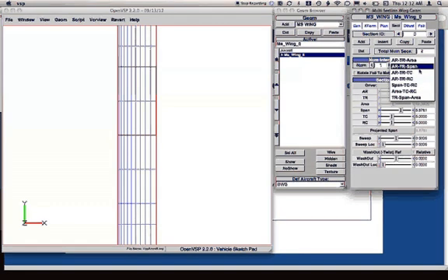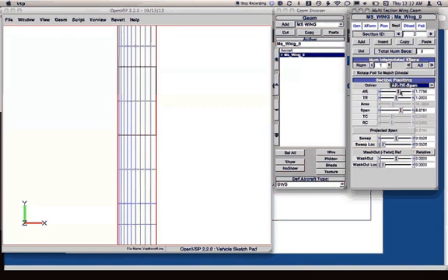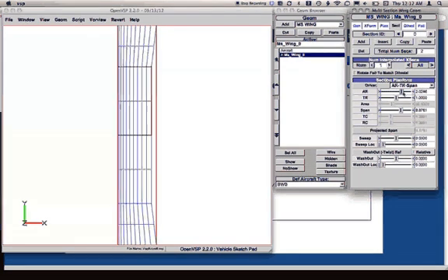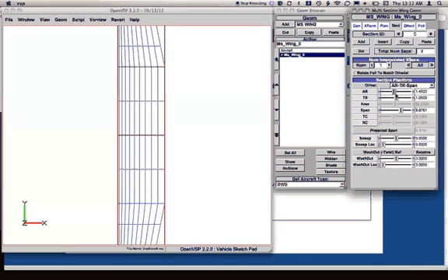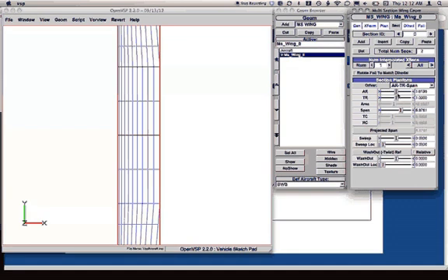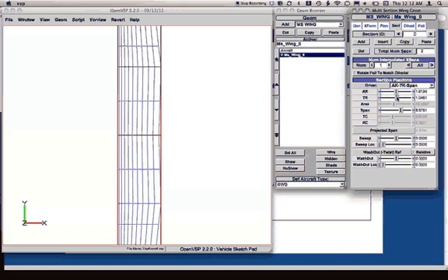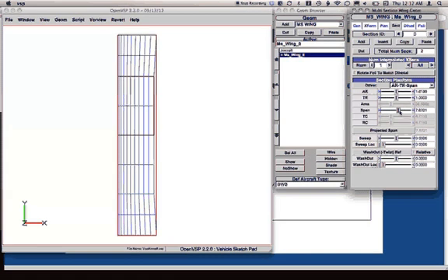So in this case, let's do the aspect ratio, taper ratio, and span. So I come in here and change the aspect ratio. Again, note I'm just working in that section 0 right now, so it's not changing the other sections. Change that taper ratio. Again, we'll keep our taper ratio at 1 here, and I can also come in and change the span and make that shorter if I need to.